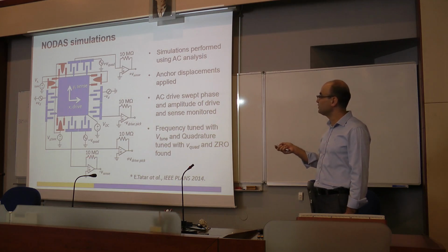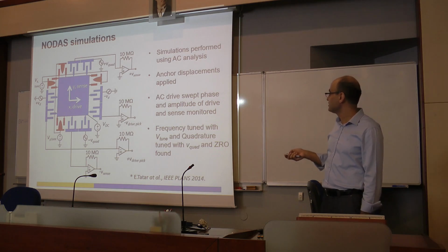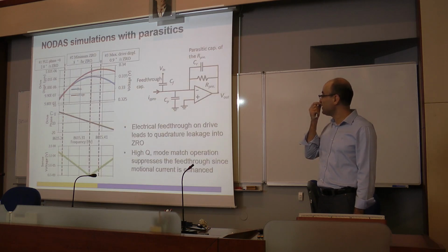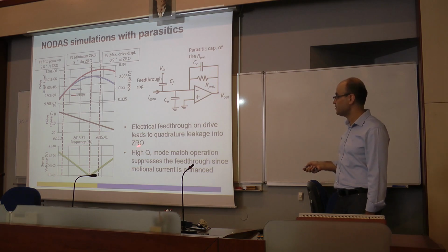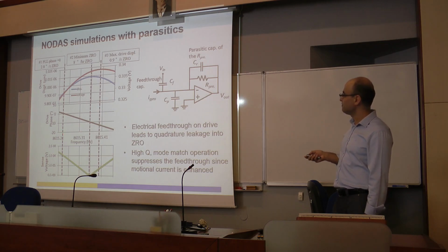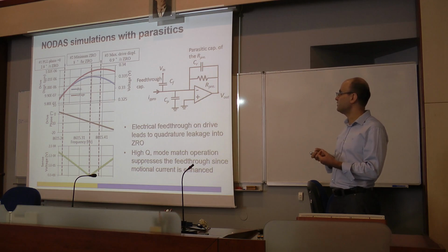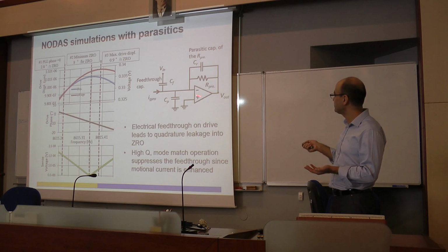This is called MODIS, which stands for Model Design of Actuators and Sensors. We use this to simulate the gyro, and this is one result. This may be very confusing to you. This is an AC analysis. I sweep the frequency and I look at the phase and displacement. What we showed at the end was, even though you operate in ideal conditions, whenever you apply stress, you end up with an offset, which is 8 degrees per hour here. And you have to pay attention to other stuff as well.